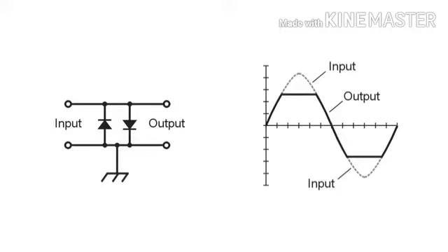The loudness of the signal would be overwhelming, and in fact, if you were wearing headphones, you might actually feel pain in your ears. Well, they used to devise a circuit in order to prevent this so-called blasting, and a very simple way to do that is to take two semiconductor diodes and connect them in reverse parallel like this.